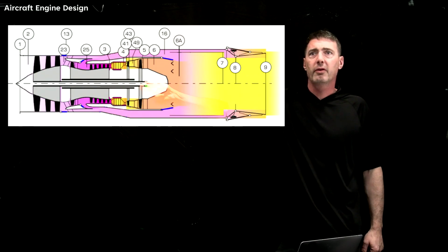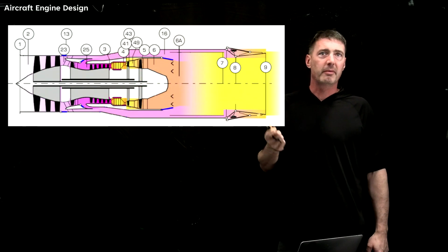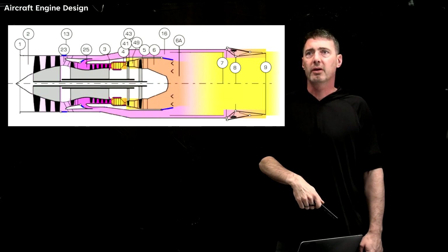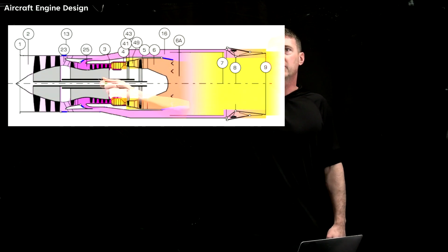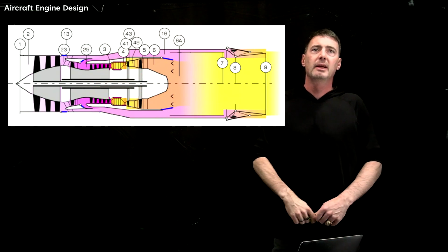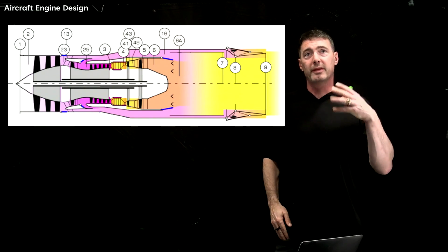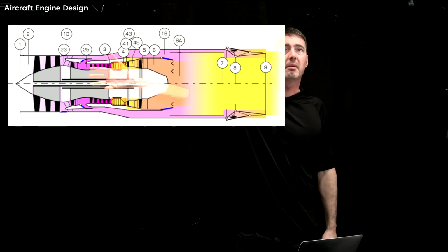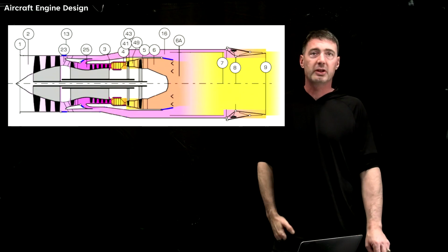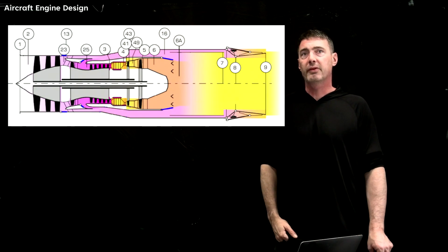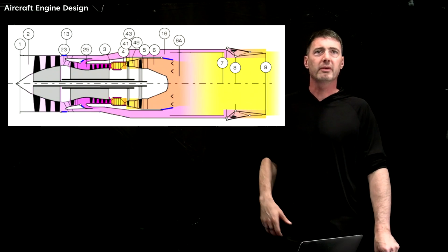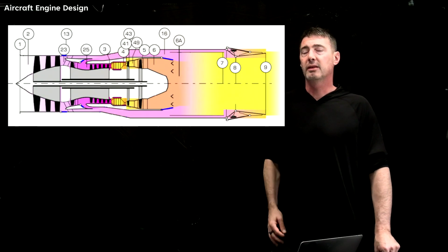There are also bypasses that come through here. This diagram is not going to show you some of the bypasses that you might take off of the turbine. This diagram is actually showing you one bypass that's coming out after this. And by the way, when you're on an aircraft, the air you're breathing is actually the air that's been compressed up front, and you're taking a bleed off of that. So it's called jet engine bleed. It's used throughout the aircraft for many things, including for humans to breathe. Yes, they put a filter there, but it hasn't touched any of the fuel system yet.